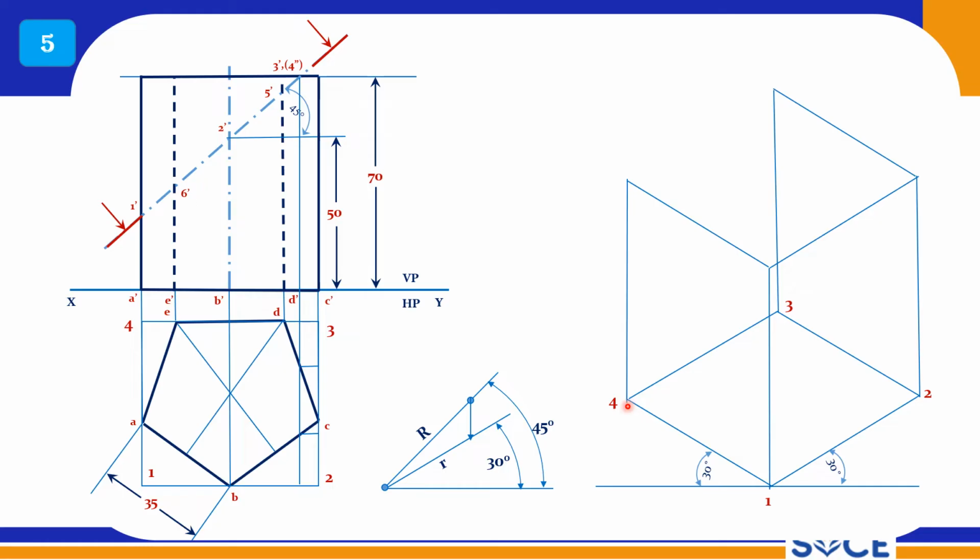Now draw the box as we did in the earlier problem, and mark A. So measure this distance, convert it here and use that here. 1 A, and you have B, C, D, E. So totally 5 points. Now all those points you get on the top surface also. So now you measure this one distance from the front view.